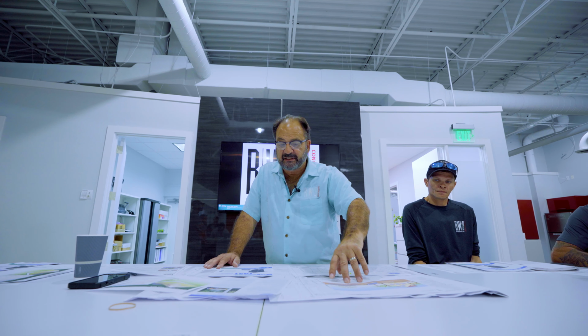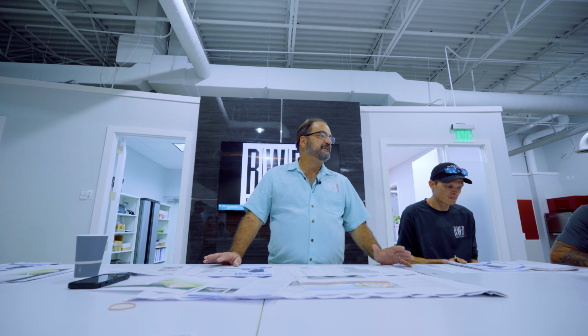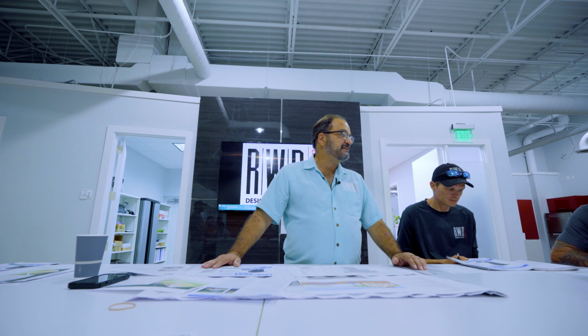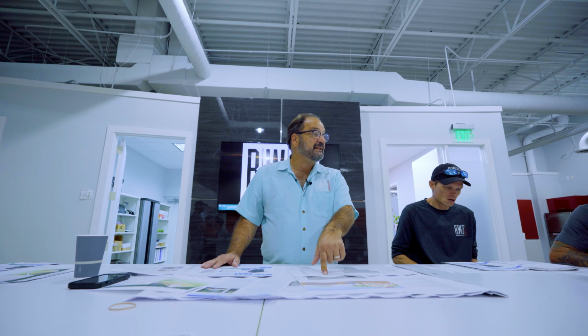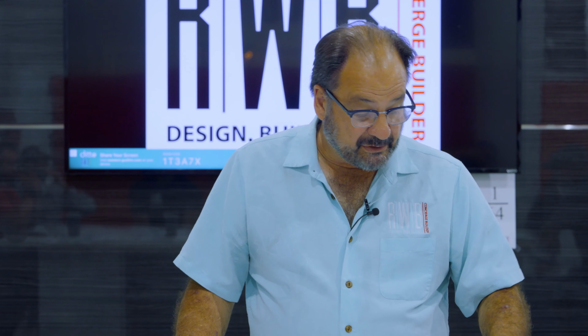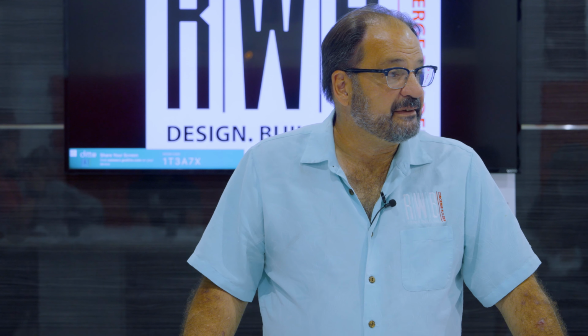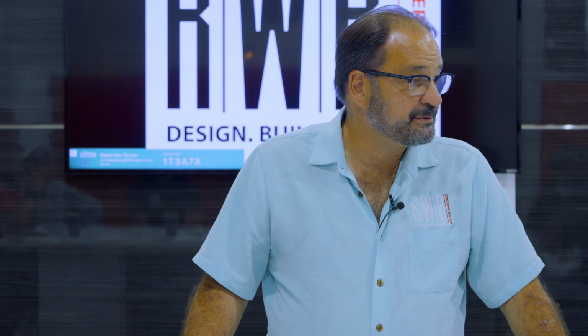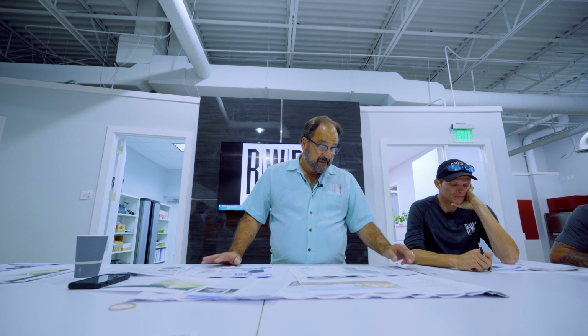After you get this and you get your civil plan, now you're looking at this. And again, it's easier to fix it on paper than it is to fix it in reality. Okay, you look for things that are an issue, like this 10.5-foot wall. You look for things that are going to be a conflict later, and you try to address them before you go too far. If you don't, they're going to bite you in the butt later. Everybody understand that?